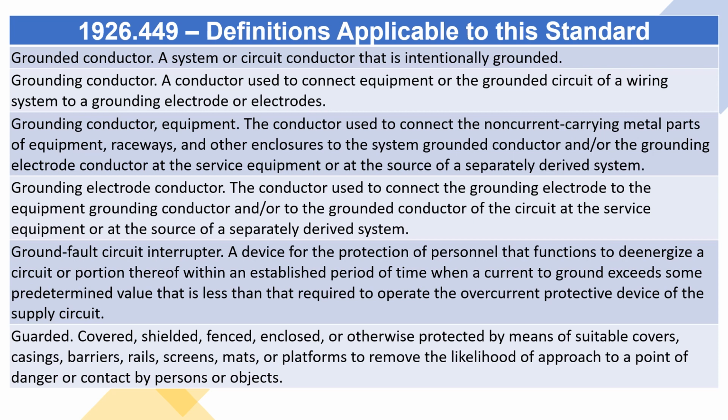Grounding electrode conductor. The conductor used to connect the grounding electrode to the equipment grounding conductor and/or to the grounded conductor of the circuit at the service equipment or at the source of a separately derived system.